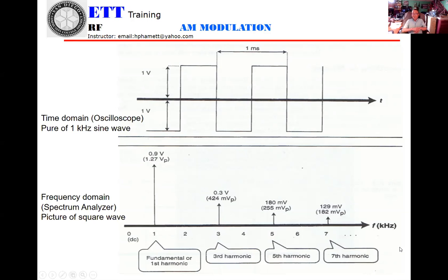So basically, the spectrum analyzer is the frequency domain. It can tell you at a certain frequency what the value of the signal is. They are sine waves, but you cannot see the sine wave. A sine wave only displays on the oscilloscope, not in the frequency domain. So when you look at the two pictures here, you must understand the second one.